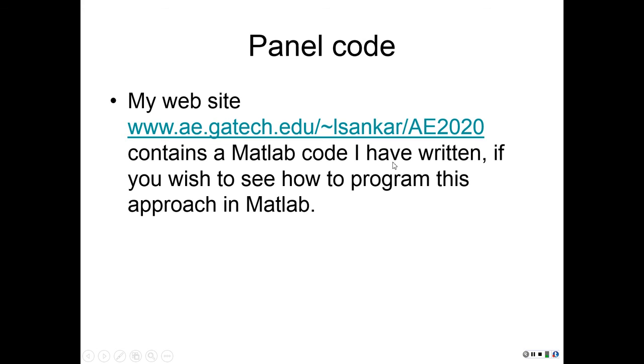On my website, I have a panel method. You could just click on it. It's written in MATLAB. I have also included those things in our ebook, the complete listing, sample input, sample output, so that you could see how these things work. Industries normally use a more robust program such as Xfoil, because my program can only compute the lift. It does not compute the drag. How do you compute the drag? We have to introduce the boundary layer. So that's a topic for our follow-on lectures.